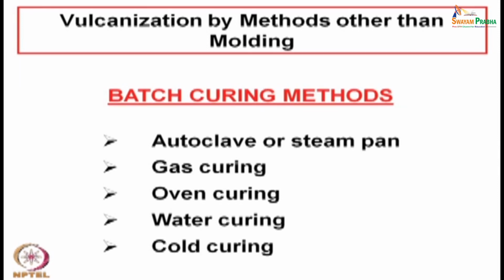Then it needs to be vulcanized or cross linked. The product, which contains those additives along with the sulfur, etcetera, needs to be cross linked. Till now the vulcanization is not allowed. Only after the complete shape is given is it vulcanized or allowed to cross link.